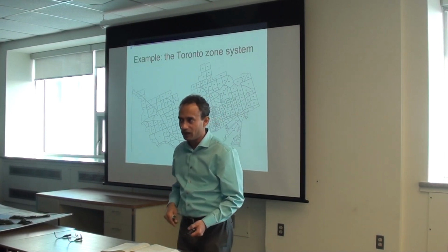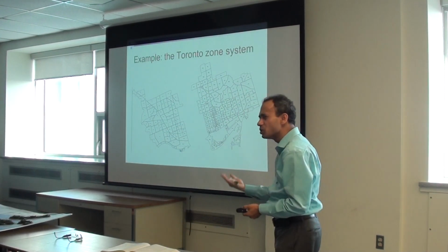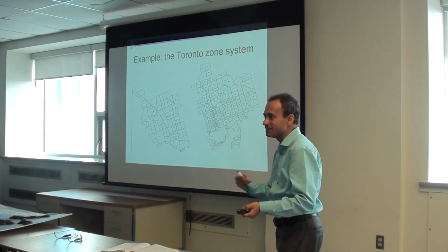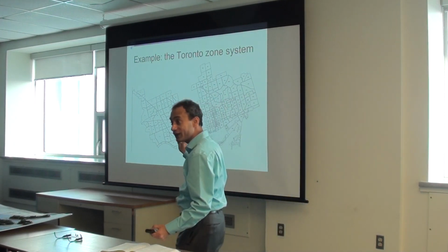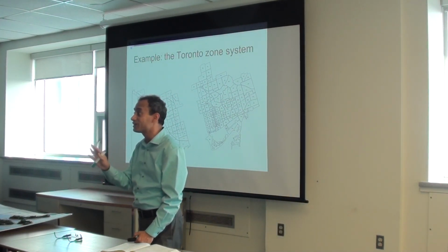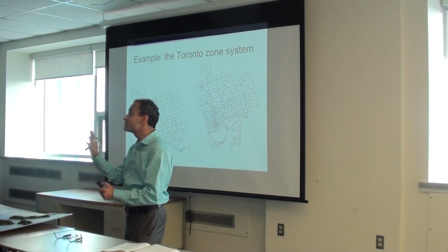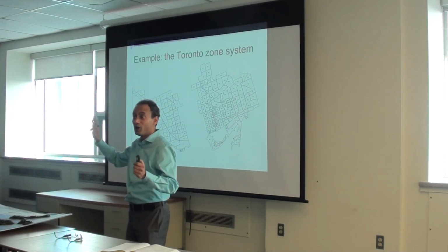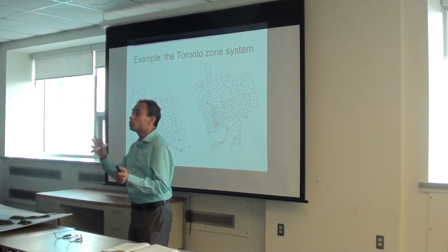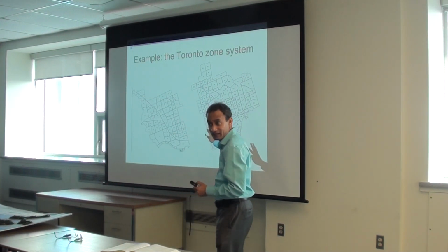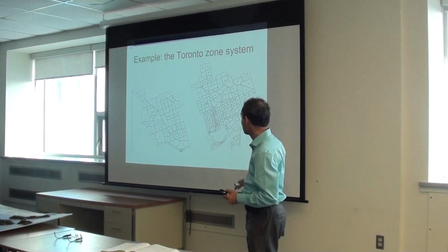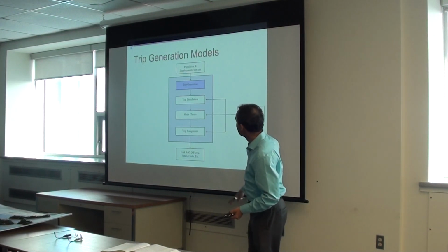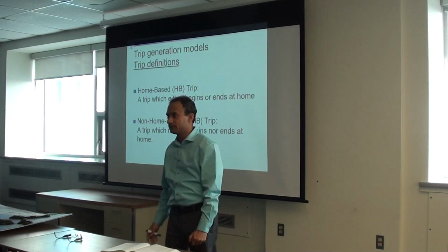Usually it's given, so I'm not explaining a lot on that. Usually it goes with the dissemination area or census tract area because we can then borrow some data. Data is an issue. And the data we are talking about here, the data that we will use, we talked about in the second lecture. That travel survey, origin-destination survey, remember I showed the TTS, Transportation Tomorrow Survey, or the Nova Track survey that we are doing in Halifax. Those are the data sources for developing those models, the behavior, the trip generation and distribution. That's what we do. But what we do is simply first the network and then also the zonal piece, and then we try to do the trip generation.